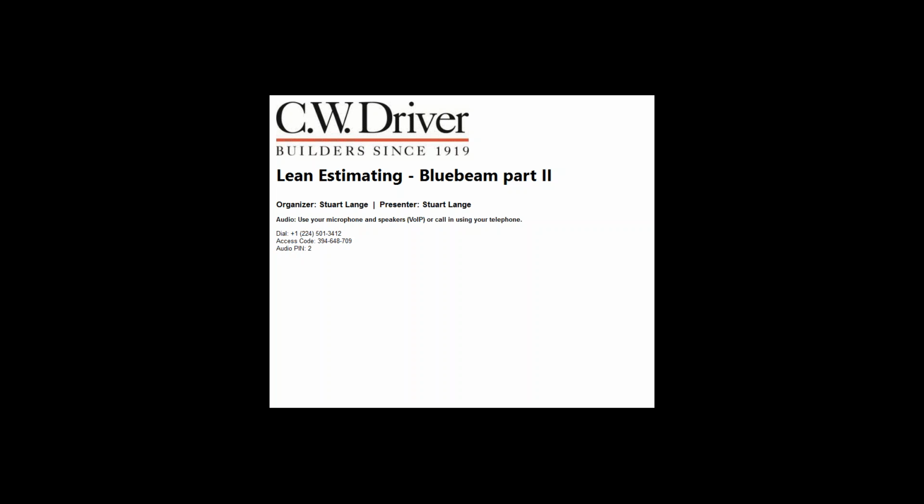So we're going to click on Link Options, double check. I'm going to turn on my highlight links. I made it blue. You can have yours probably yellow by default. It's yellow, yeah. So it doesn't really matter. Everything else you can leave the same, and go ahead and hit Run.